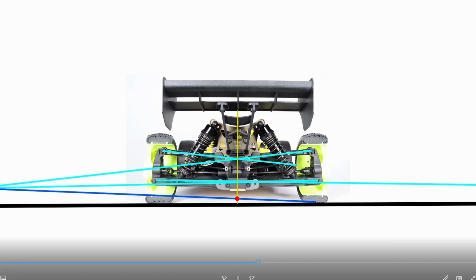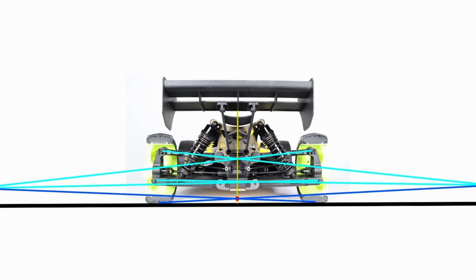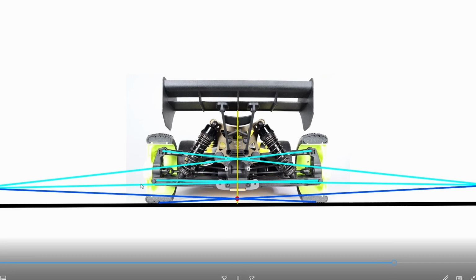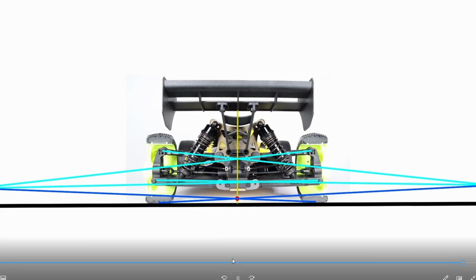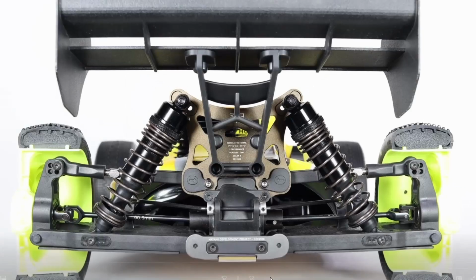Now we repeat this process for the other side of the car. And you can see that they match in this case, because the car is symmetrical. So if you have a stationary car at ride height with symmetrical left to right suspension, all you need to do is draw one side and you find the roll center. The reason we need both sides is because as soon as the car rolls or moves, the roll center will also move because the suspension is no longer symmetrical left to right.